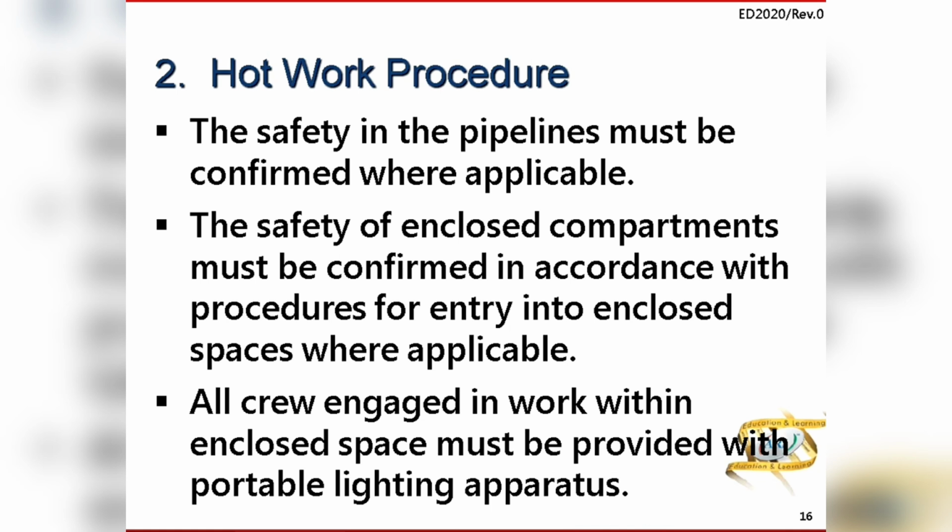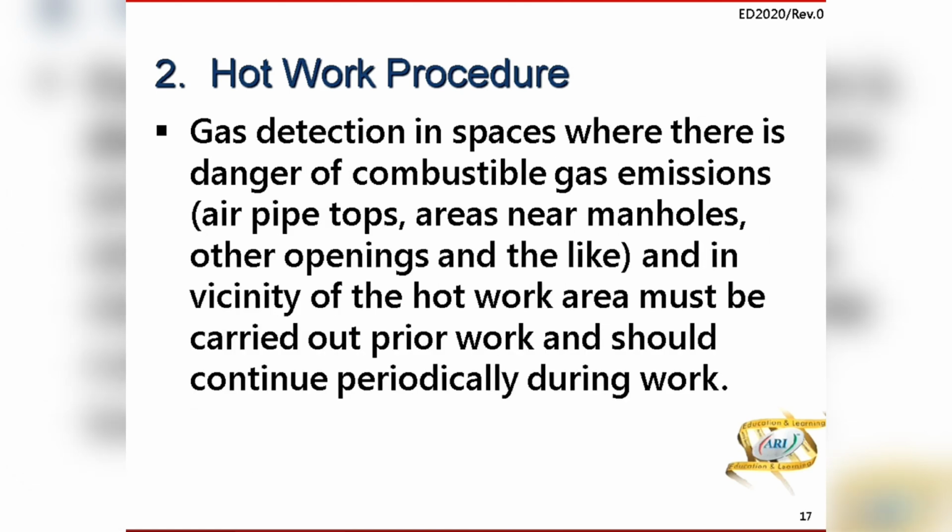All crew engaged in work within the enclosed spaces must be provided with portable lighting apparatus. Gas detection in spaces where there is danger of combustible gas emissions, that is, air pipe tops, areas near manholes, other openings and the like, and in the vicinity of the hot work area, must be carried out prior to work and should continue periodically during work.